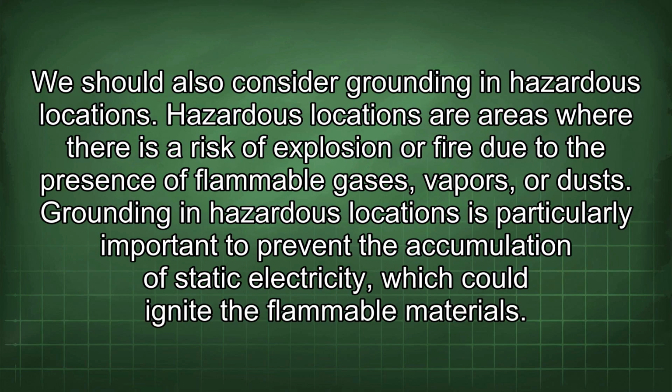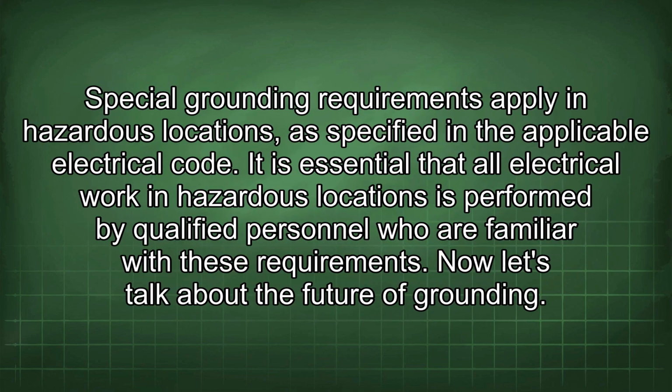We should also consider grounding in hazardous locations. Hazardous locations are areas where there is a risk of explosion or fire due to the presence of flammable gases, vapors, or dusts. Grounding in hazardous locations is particularly important to prevent the accumulation of static electricity, which could ignite the flammable materials. Special grounding requirements apply in hazardous locations, as specified in the applicable electrical code. It is essential that all electrical work in hazardous locations is performed by qualified personnel who are familiar with these requirements.